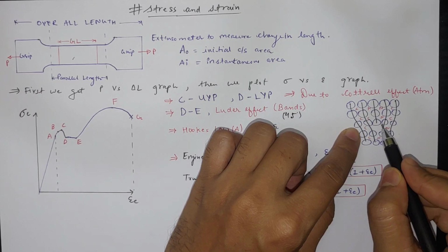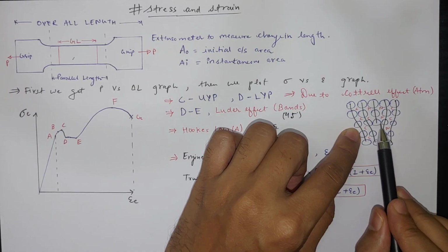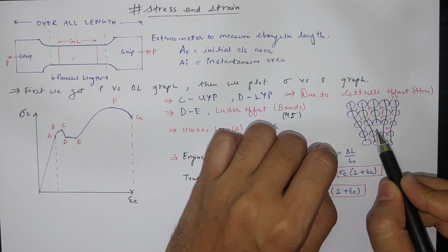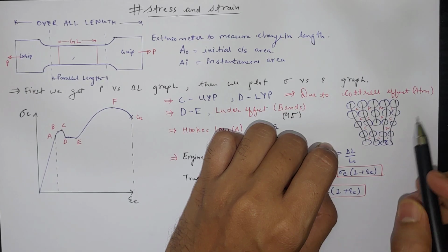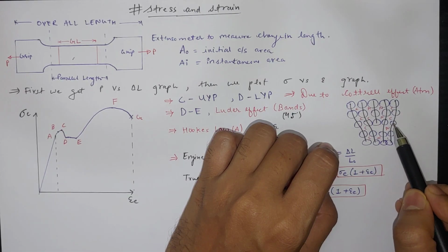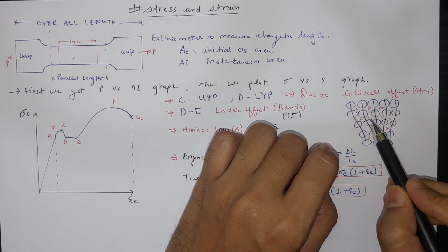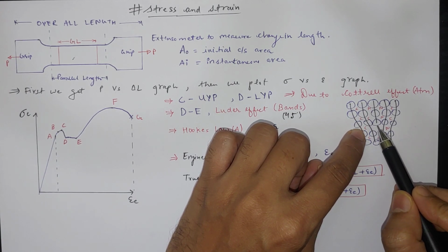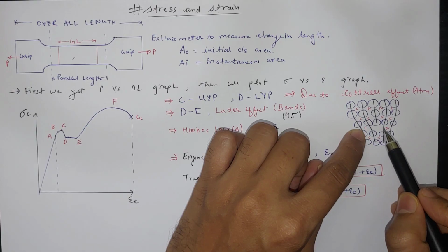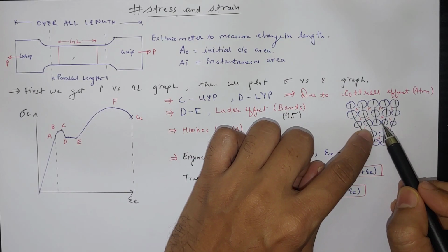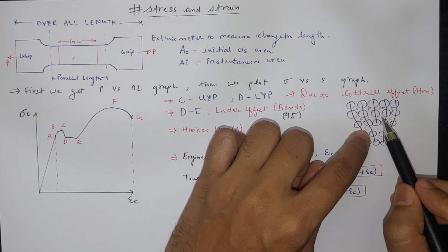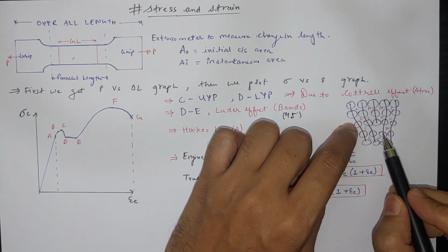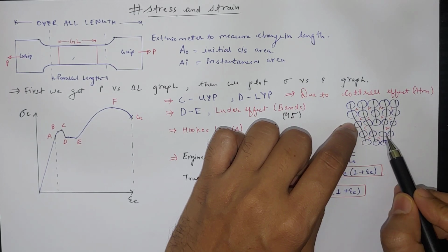Here there is a bigger space available, so this edge will not transfer to these atoms, and it will not glide out on the edge boundaries, because there is a much bigger space, so more energy is required. Now once this compression is greater than a certain limit, the carbon and nitrogen atoms will come to this location, because they can get a much bigger space here to accommodate. So they come to this location, and the carbon and nitrogen which were hindering this particular edge dislocation from gliding move away, and also much less energy is required to bond with other lines.